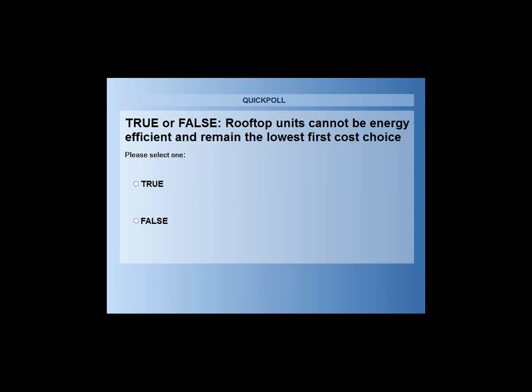While you guys are doing that, I'll clarify Tony's question. Tony's asking for DCV, and when I said modulating the people portion of the code during the occupied mode, what about unoccupied? Can I go to 0%? Yes, you can go to 0%, absolute 0%. When it's unoccupied, you can modulate the people portion down to 0, and the square footage portion goes down to 0. Both of them 0.